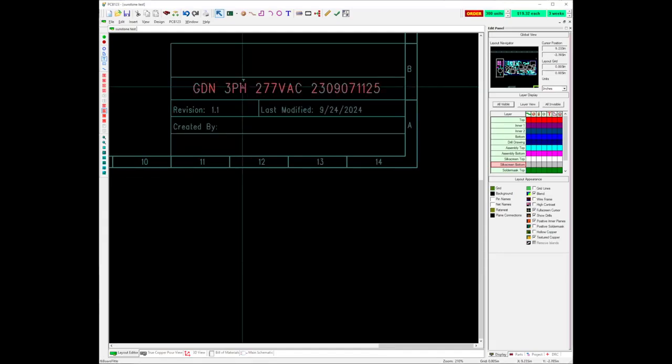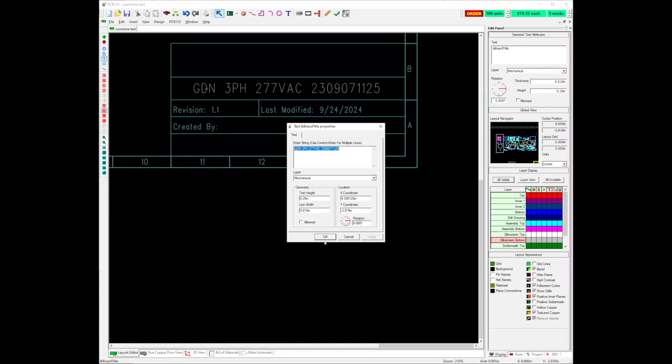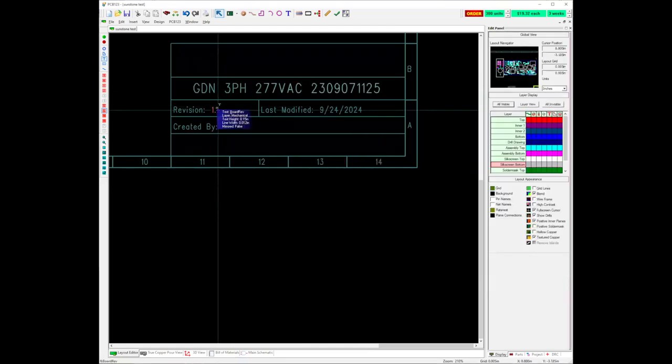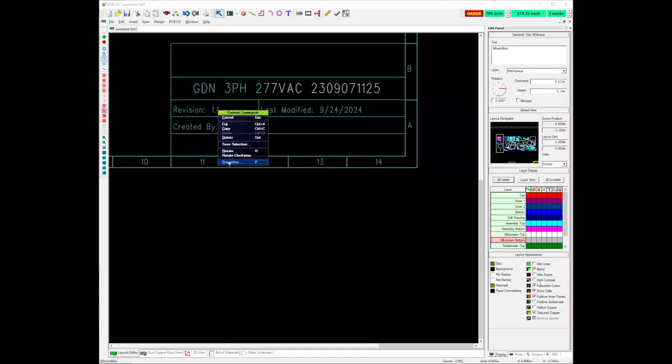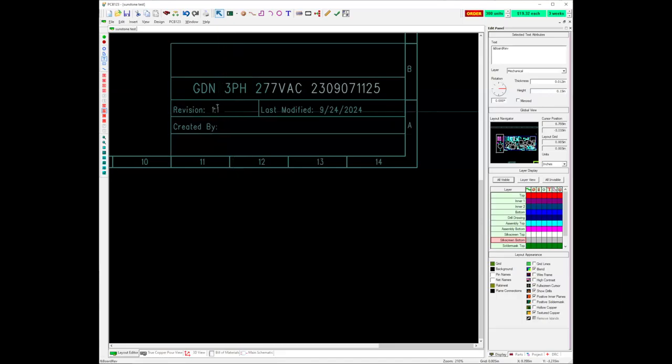And then this field here is the field that generates the order name, the part number that you're ordering from Sunstone ASC. So again, properties, paste, you paste the file name in there, and off you go. Then, in order to keep track of the revision of your board, which sometimes is pretty important, especially if you're rolling the rev for a minor thing, you can change that here and just add a revision name number. And this is the revision number that goes on the order form.